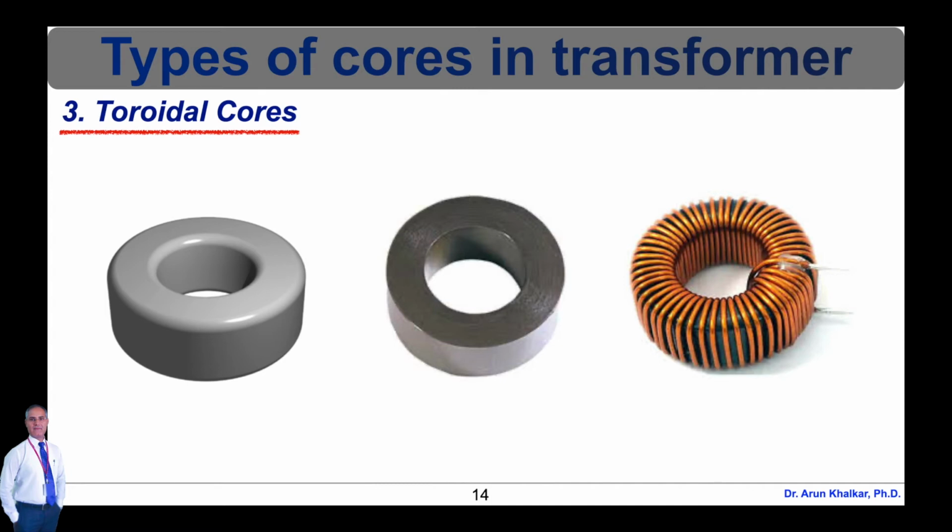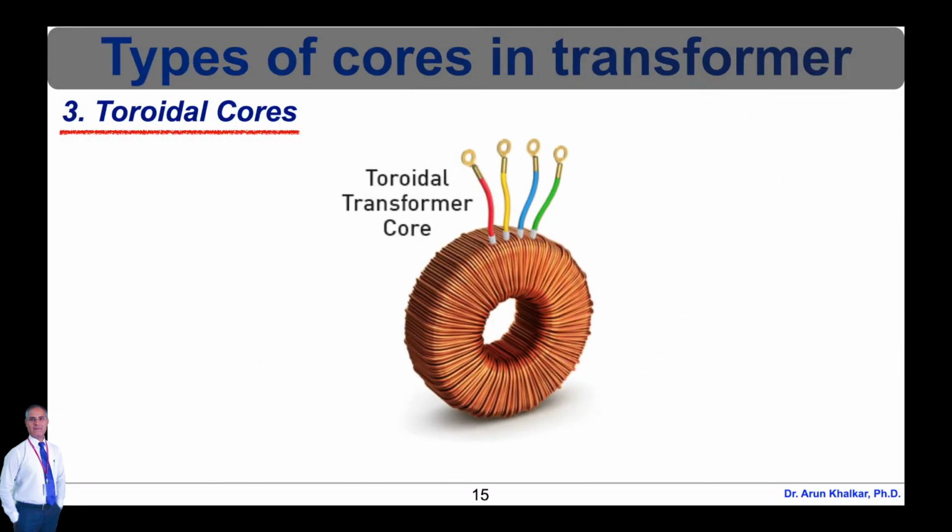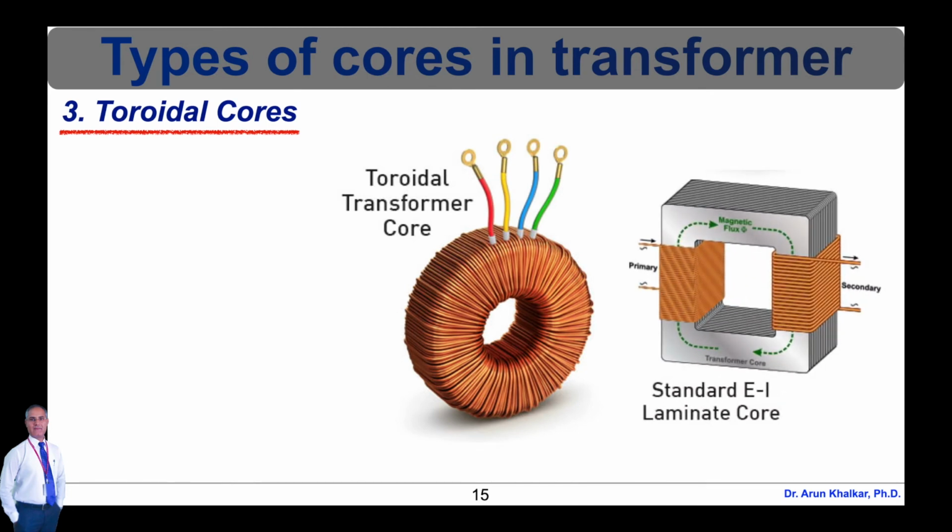This minimizes length of wire needed and provides a screening to minimize the core's magnetic field from generating electromagnetic interference. Toroidal transformers are more efficient than the cheaper laminated EI types for a similar power level.